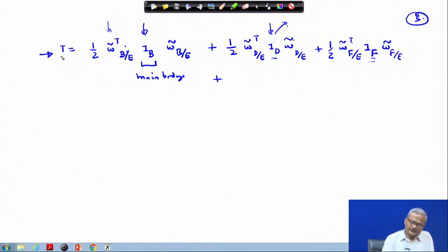On the other hand, if we write the same thing for the torque equation, because we have to write along a particular axis, in that case the torque will be a vector. So along the 3 axes you have to write, and all of them are oriented along different axes and are moreover changing with time. So for this we reduce all of them to the body axis and then work.